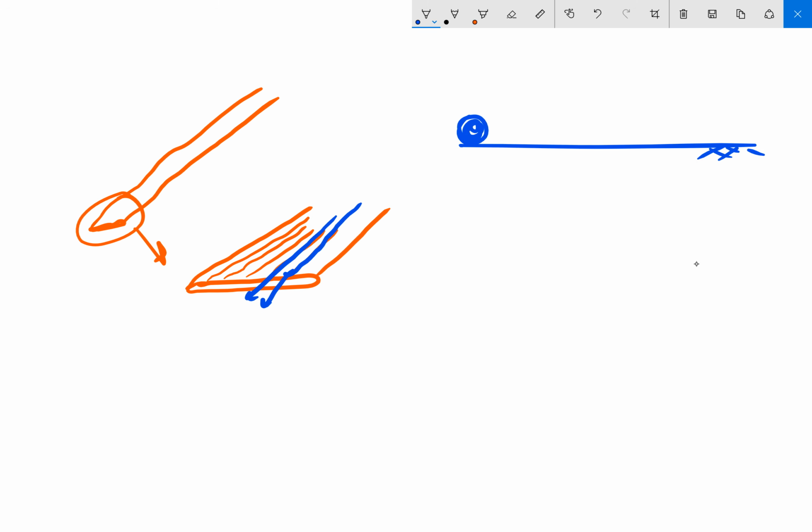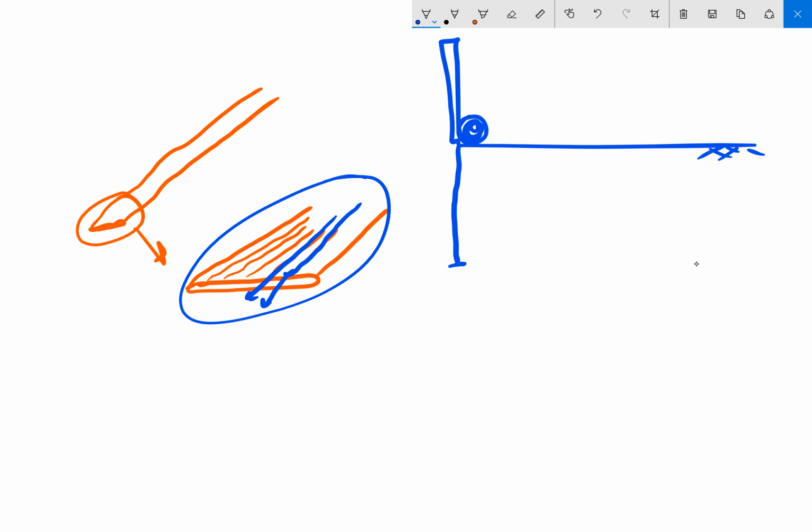attached to these big mandrels, these big machines, and the machine grabs onto this roll and it pushes it down into the soil. And it has this sacrificial mandrel that once it gets down to the desired depth, it detaches from that mandrel and it just pulls itself back up, but it leaves this PVD or wick drain down into the ground.